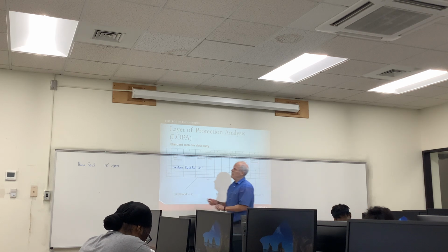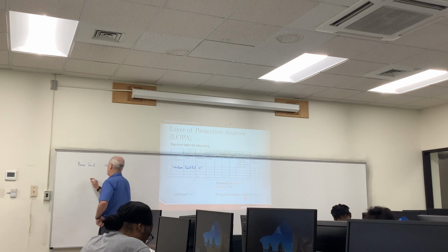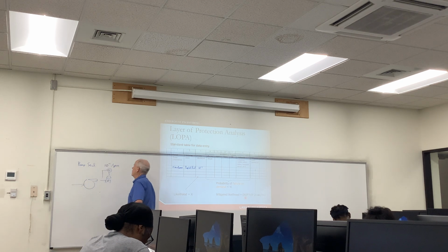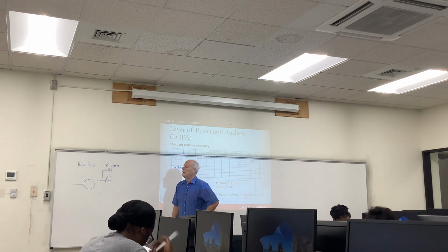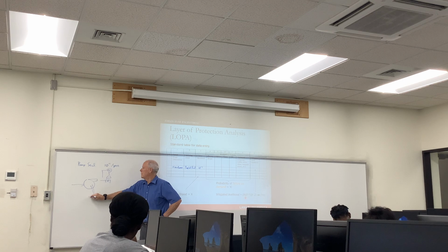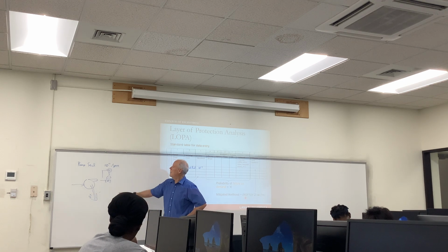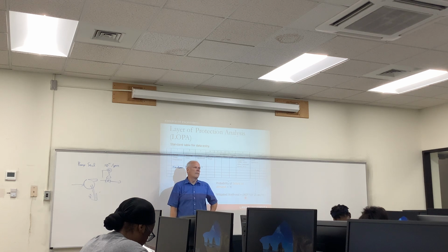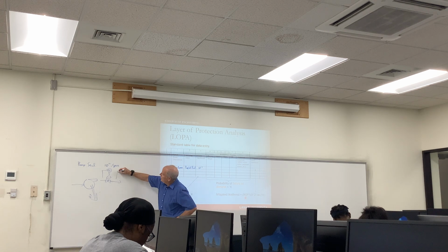We've got a pump here, it's a big pump. Like on the DCS? Big pump. Right, got a control valve here. Flow control. Okay, the pump seal fails, oil's going all over the place. Right? What do you see in the DCS? Your valve's gonna open all the way. Valve opens all the way.